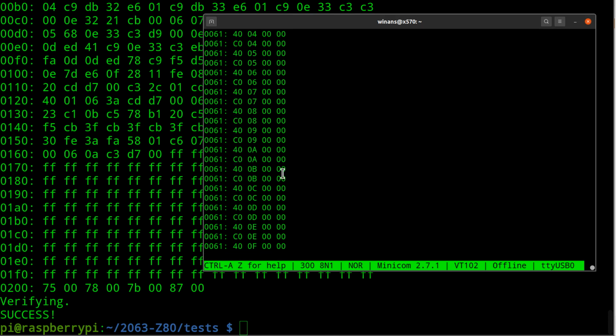But this one takes so long to print, is my point, that by the time it actually prints one of these lines, the counter is raised by over 64 interrupts, which means this is taking just a little bit more than maybe a half a second to print one line, right? Because the counter's running 64 out of 152 is a little bit more than 2 hertz, maybe 2.5 hertz, and it's counting along, and we're wasting too much time, and we're missing interrupts here, okay?